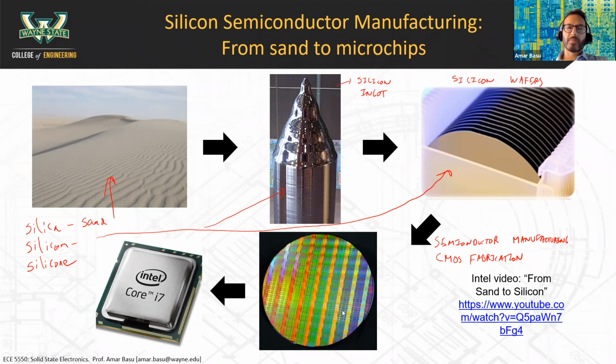And there are processes called lithography, where the transistors are patterned. There are processes called metal deposition steps, where very, very thin films of metals are deposited to make interconnections between the transistors. And then the transistors themselves are made using processes where the silicon wafers are put into furnaces and you flow a process gas through there that forms P regions and N regions.